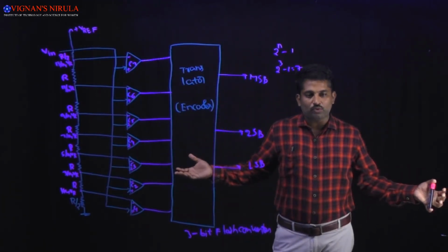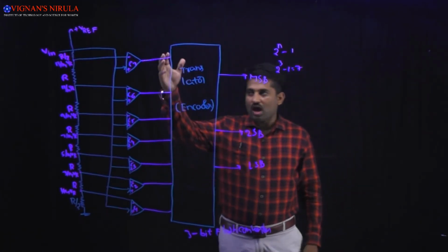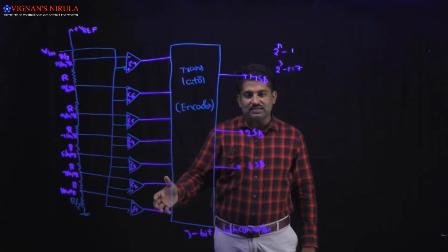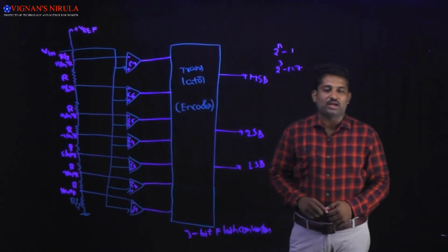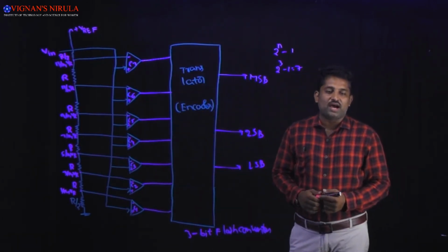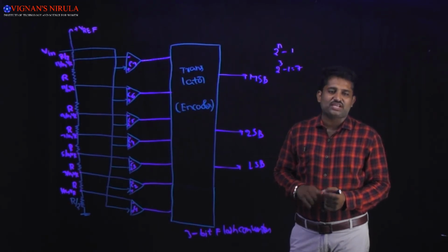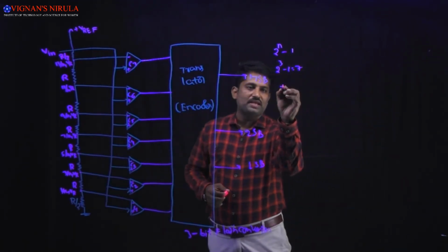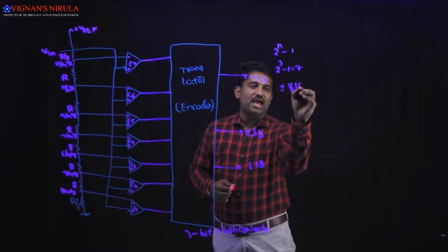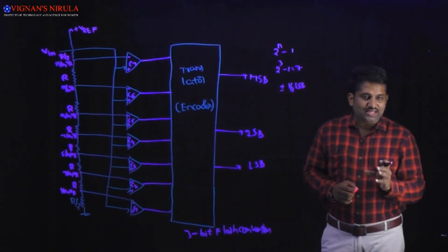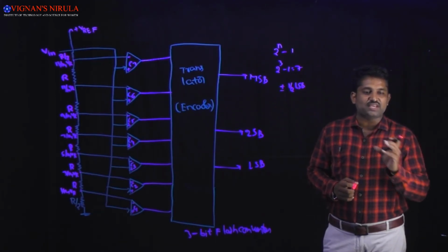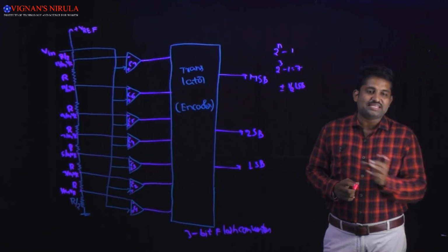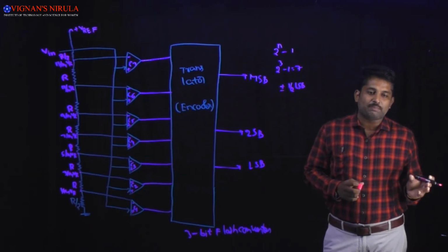So what I am going to conclude is the output code of the comparator is converted into digital data with the help of an encoder, and we all know that the quantization error will be equal to plus or minus half LSB. Thus, for the ADC, the maximum input signal frequency, the sine wave input voltage, is digitized accurately by plus or